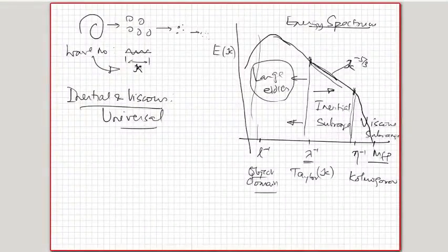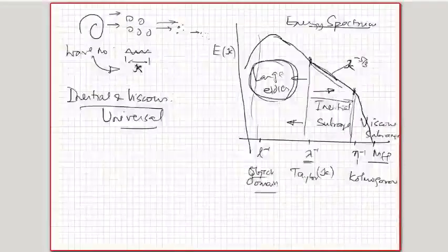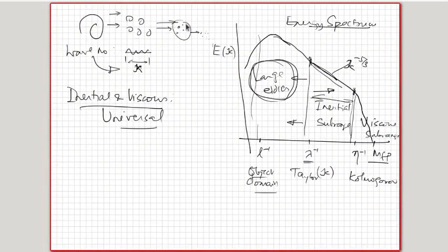What does it mean? It means that irrespective of what is the production mechanism for these eddies, the way they transact energy from the large eddies to the medium-sized eddies and the medium-sized eddies to the small eddies, which happens in the inertial subrange, and the small eddies to heat in the viscous subrange, this mechanism is more or less the same irrespective of whether the wakes are produced by the aircraft or turbine blades or automobile or any such source, or be it even atmosphere.